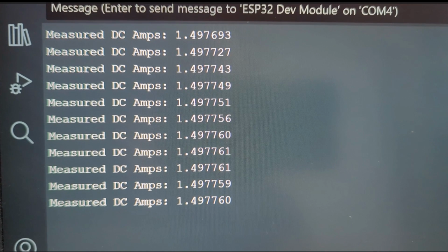So I'm going to pause it right there. But the idea is the current flowing through the shunt, which is right now at about half its rated power. At 100 microamps, it's at a very low power, so self-heating basically doesn't come into play. But when we shove a higher current through it, that's when you can see the effects of self-heating. And remember, when a material heats up, its resistance goes up. If our shunt resistance goes up, the voltage drop goes up. Well, if the voltage drop goes up, the calculated current also goes up.